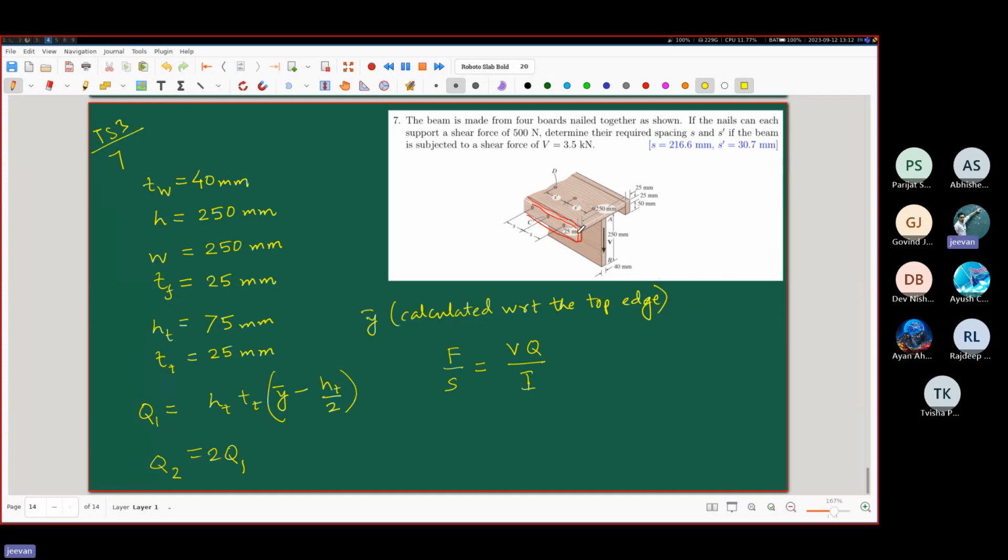The same kind of mistake which we were doing earlier with the table-like structure. So you have to consider both these bits, and then only you can say that whatever the remaining piece is, that will be having the minus of Q of this. And again, the argument is that you are basically considering parts which are vertically symmetric. But if you don't want to go into all of these complications, just proceeding with this Q1 thing where you are considering only one bit, just one row of nails, this is perfectly fine. Proceed like this. There is no problem.